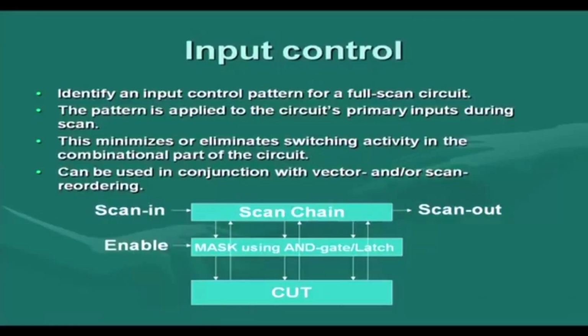So, we can do a static simulation and find out the power consumption corresponding to the individual gates for different input patterns, and accordingly we can select one input pattern to work well for the entire circuit. If we do this, static power is reduced, and at the same time the switching activity gets eliminated. There is very little switching activity; the only switching activity will come when this mask comes into existence. At that point there will be some changes, but otherwise not.